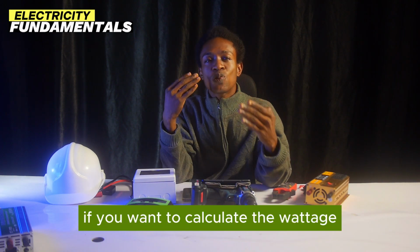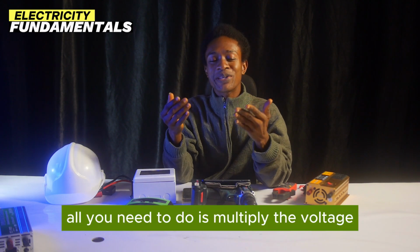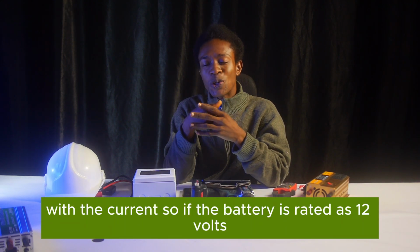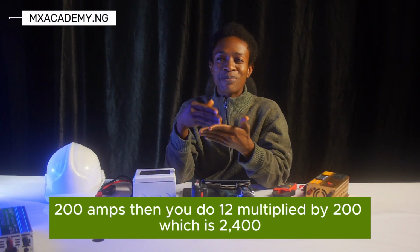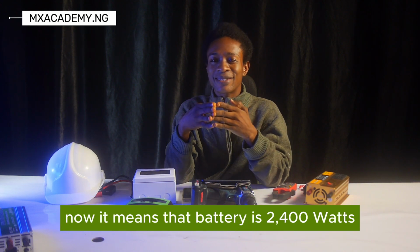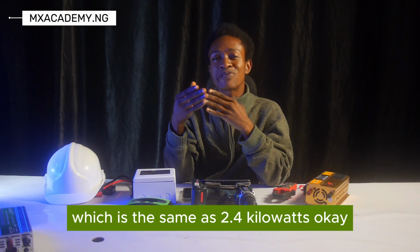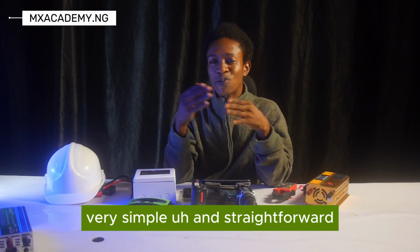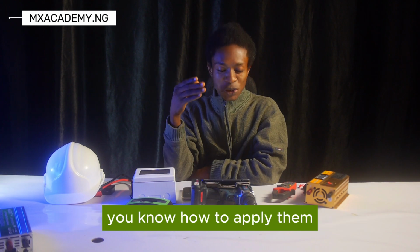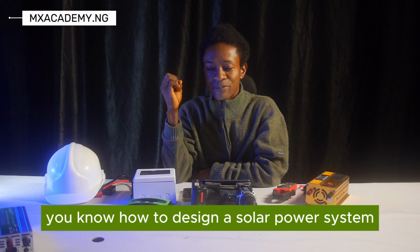Simple. If you want to calculate the wattage, the kilowatt hour of a battery, all you need to do is multiply the voltage with the current. So if the battery is rated as 12 volts, 200 amps, then you do 12 multiplied by 200, which is 2400. It means that battery is 2400 watts, which is the same as 2.4 kilowatts. So it's a 2.4 kilowatt hour battery. Very simple and straightforward. Once you know these things and how to apply them, you know how to design a solar power system.